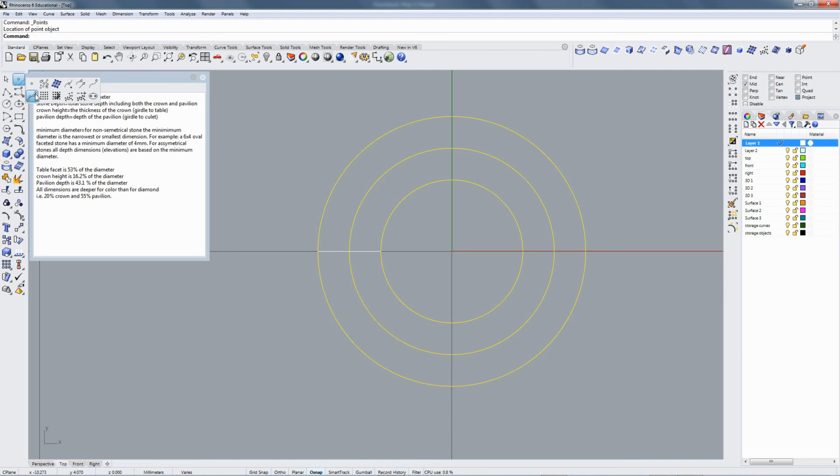Make sure the seams are all in the same orientation and the same location on the circles, and then type in a number. Oh, sorry, I have to accept that first and then type in the segments. There you go.